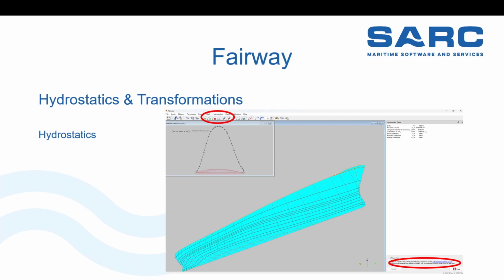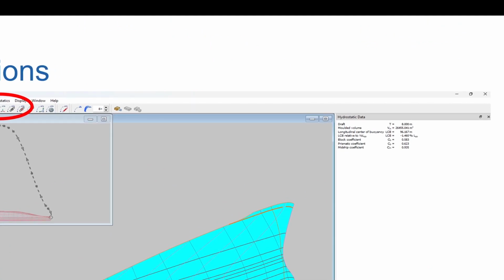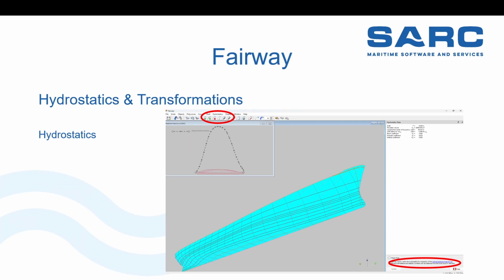If you have some low point here, then you have a partial frame, a frame that does not extend up to deckline or beyond, and that will have a very small area, so you will have your regular sectional area curve, one frame down below, and then the rest. So you'll get a loop in your sectional area curve. If it looks like this, then the hydrostatics are good. Hydrostatics are listed here, draft for this draft, and some data on what you have just built.